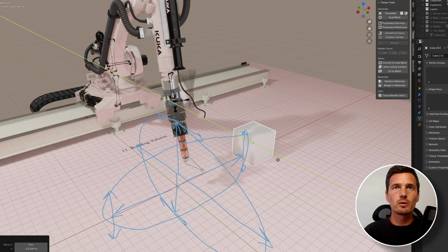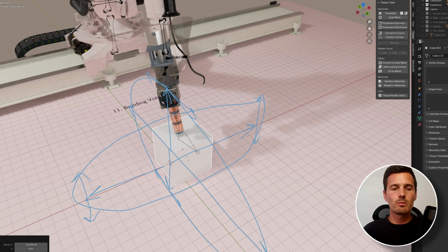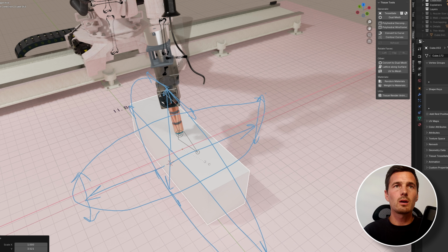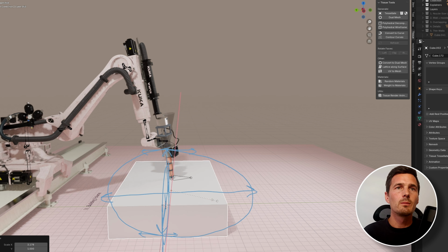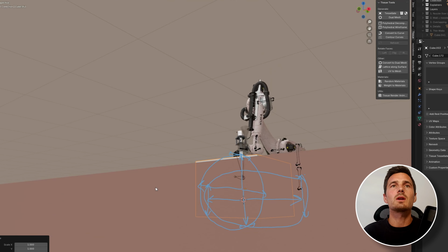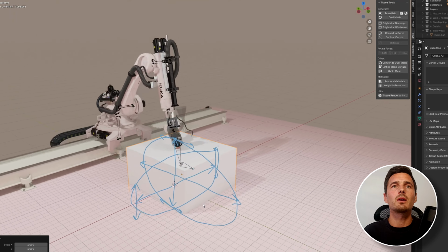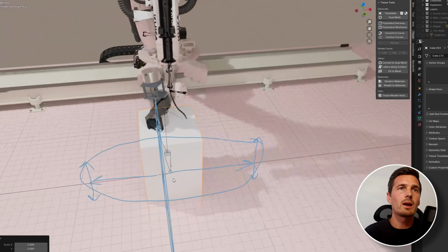So your print volume is directly affected by the movement that your robotic arm can make. Something within this cube is possible, but as soon as you go higher, you see that it goes out of the boundaries of the robotic arm. So if you want to print higher, most of the time that means X and Y have to be smaller.